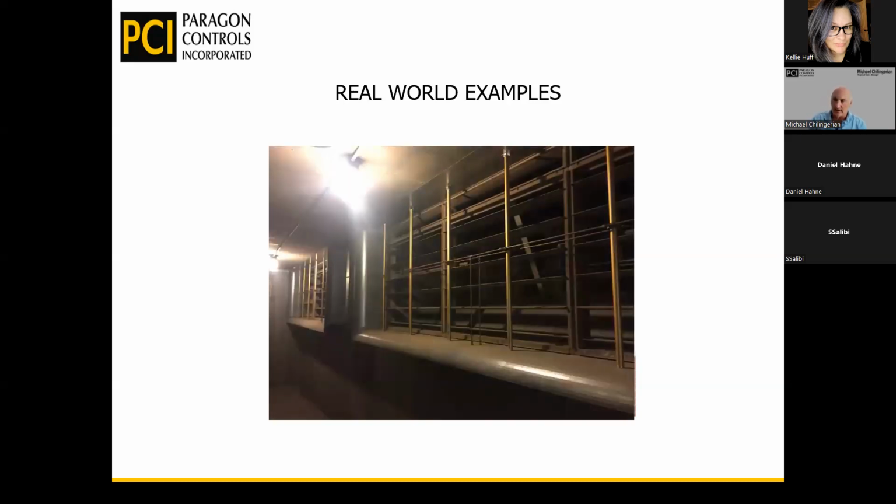Here's one that was built, I'm thinking, 10 or 15 years ago. This happens to be at Sandia Labs. A couple of big air handlers within the building. Just to the left of it is a shaft where they're bringing outside air into the building, feeding into these outside airflow stations. You can see that the averaging pitot tubes again are at right angles to the damper, so we can get a good average across there. Always at right angles and always before the damper. That's like the basics.